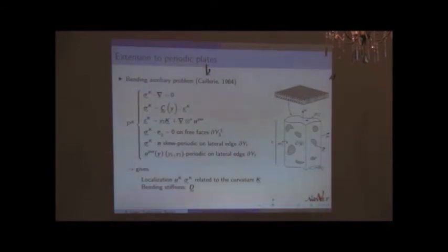This auxiliary problem tells you to just apply on average a curvature on the RVE. Just curve the RVE, or torque the RVE on average, and assume periodic boundary conditions. Conceptually it's exactly the same. It's just that you have a 3D RVE instead of a line which you integrate through the thickness.